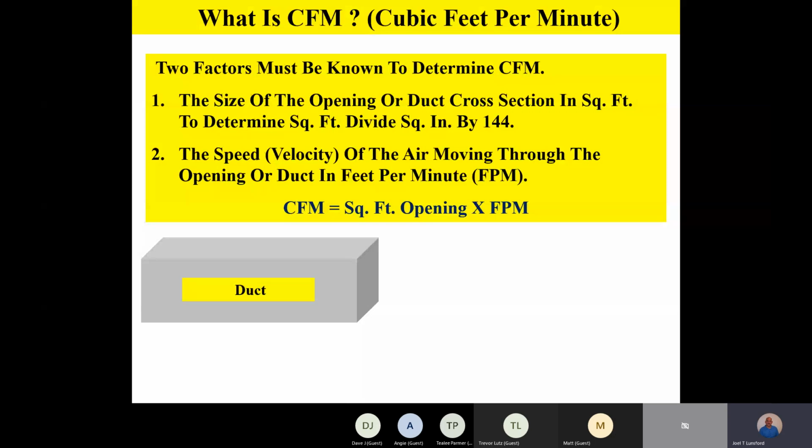Rectangular duct will give you the equivalent airflow of a round duct. So that's the third component on the air duct calculator, is we can always find a rectangular equivalent. So in our example, again, we've got about a 13-inch round duct in the round duct window. And down below, it looks like we've got about a 14 by 13 for those numbers down there that would give you an equivalent airflow. Now remember, this is equivalent airflow, not the amount of sheet metal used to actually make that duct. So it's important that we understand that this rectangular equivalent dimension has to do with equivalent airflow.